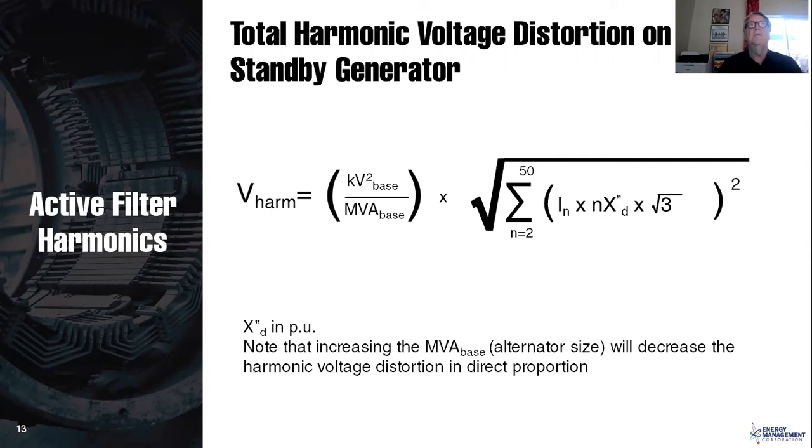This is kind of Ohm's law. You multiply the harmonic currents times the impedance, you end up with harmonic voltages, and therefore the higher the impedance, the higher the harmonics. So you can get very low voltage distortion when you're on the utility transformer. Then you switch to a standby generator, and all of a sudden your voltage distortion goes way high. So we are trying to keep voltage distortion, as we'll mention later, down around 8%.